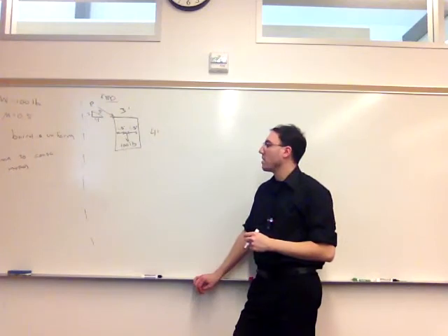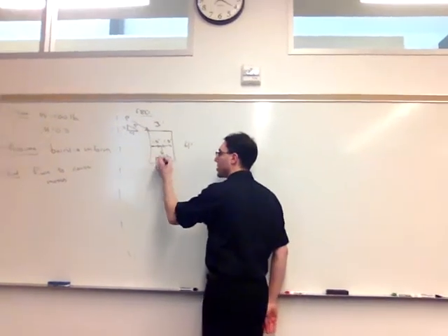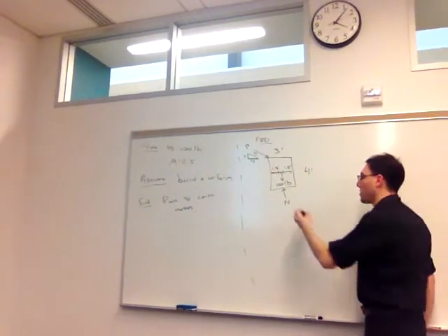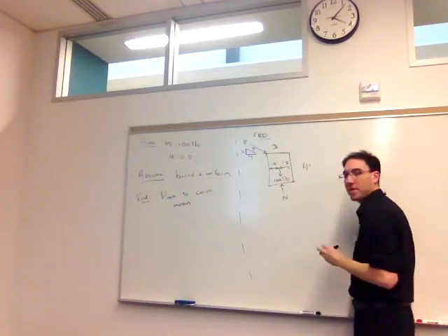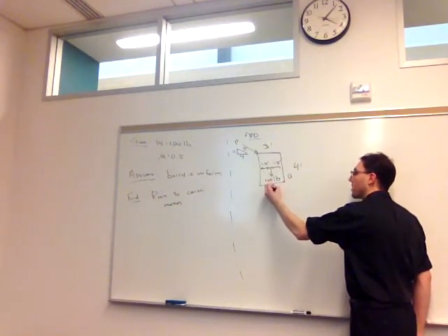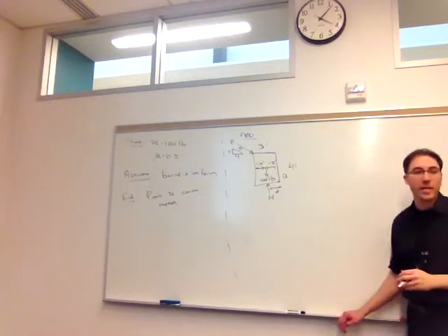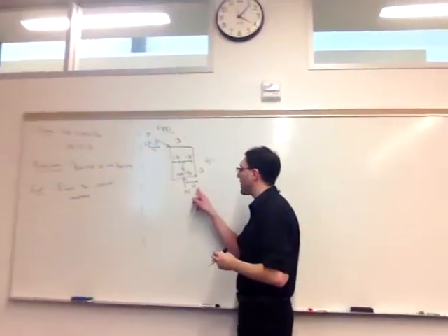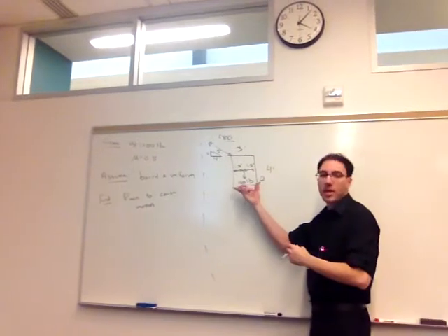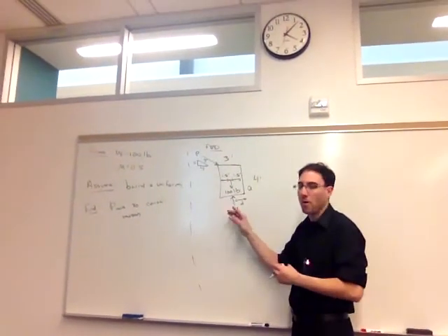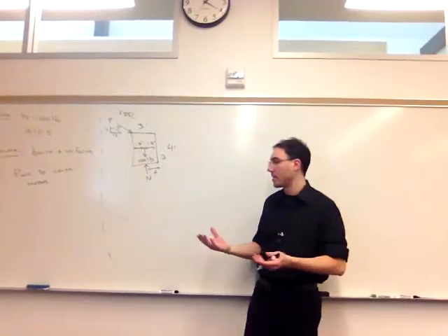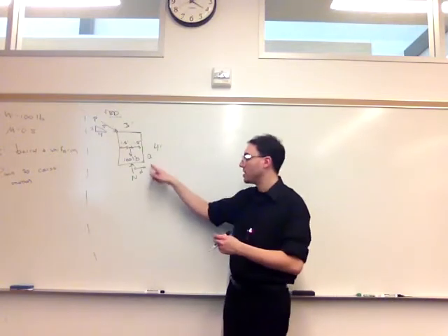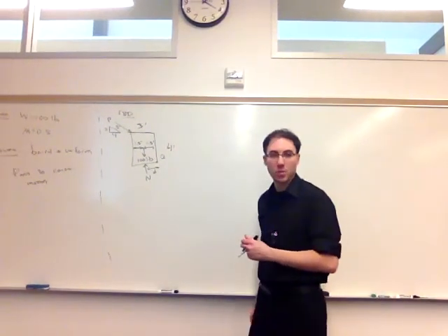What other forces act on the barrel? Normal force, this is a surface in contact with a surface. So in this case, we do have some normal force. And this is where if we do have to consider tipping, and in this case we do, I'm going to say that that normal force is a distance d from the point we presume it's going to tip about. There were cases where we didn't have to include that distance. If we didn't know any of the length dimensions of the barrel, we wouldn't be able to do a moment equation, and we could ignore it. Or if it's a point in contact with a surface, there's only one place the normal force can be. So two surfaces in contact, that's where this comes up.